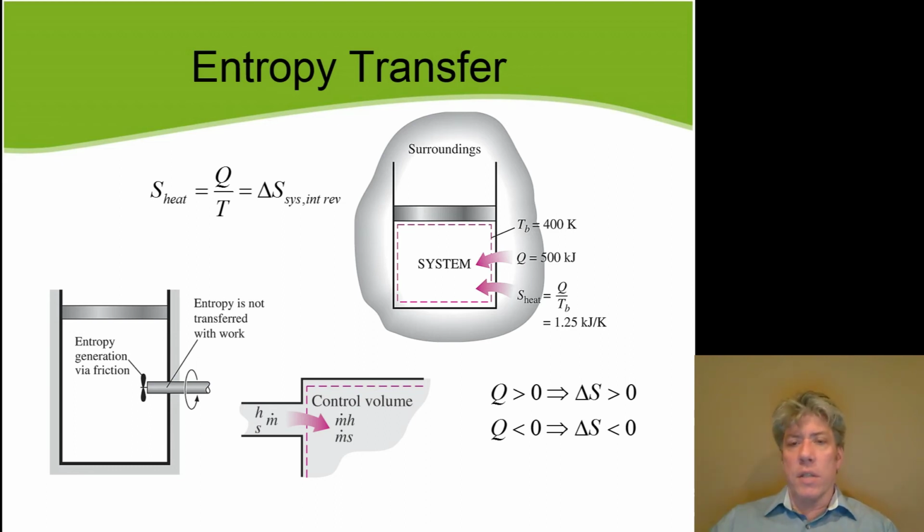And the reason is because of friction, for one thing. Of course, bearings are used to minimize that. But you've got current flowing through copper wires. Copper has some resistance. That's another irreversibility. And all these things add up so that the transfer of energy from one form to another, both even being a form of work, right? Shaft work to electrical work, is not 100% efficient. And so one of the big principles I want you to get out of this class is you really want to minimize the number of times that energy changes form.